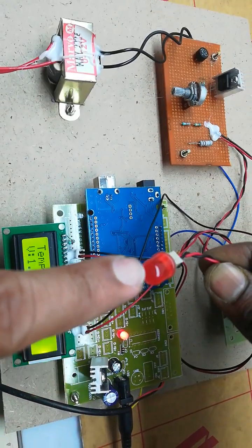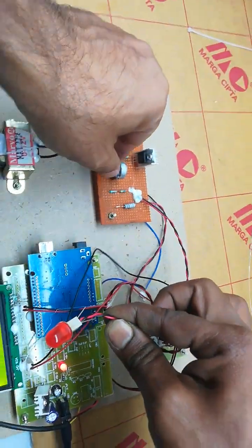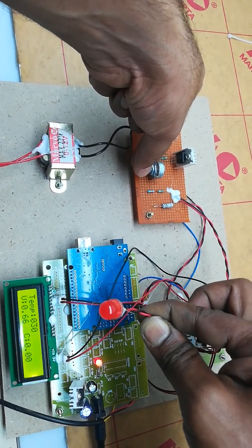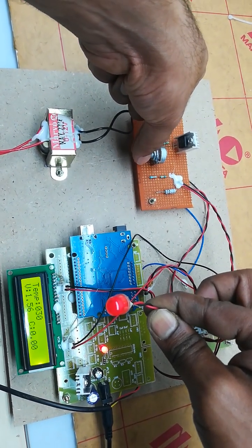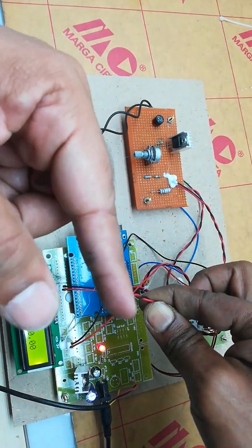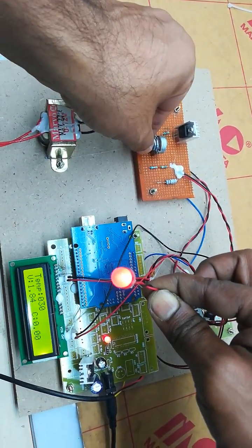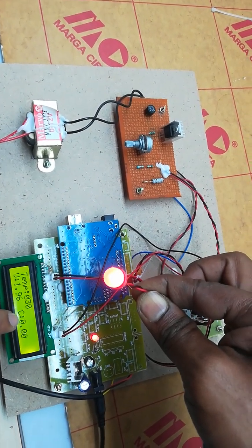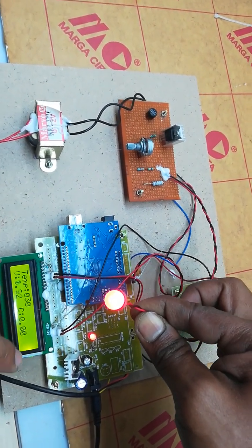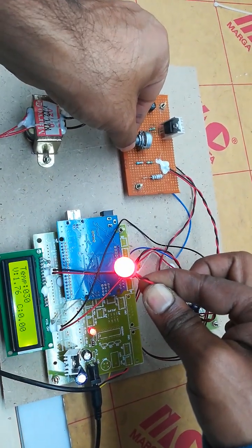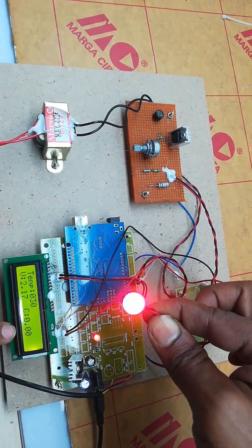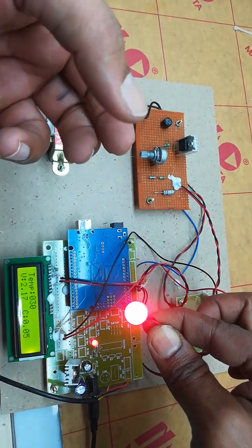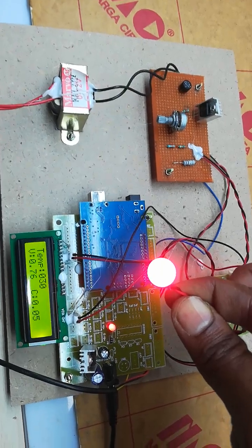Why? Because the LED is not on, so current is not drawn. I am applying voltage by rotating this, very slowly. Then the brightness increases. When brightness increases, the voltage is increasing, and it is not showing current, because current triggers after some point. Okay, 0.02. It consumes current in a discrete way. That's why sometimes it shows current, sometimes it does not.